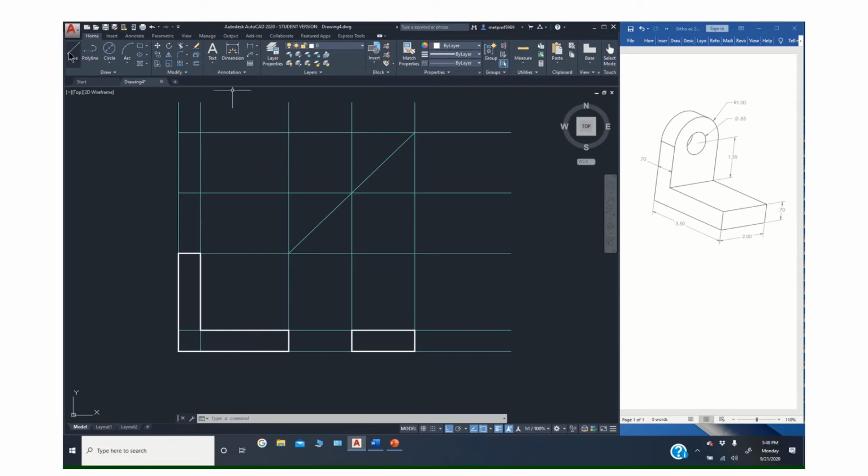So if I start like this, it's kind of a good starting point. Again, think about that face, and it's going to have a hole, but it's rounded off. So there's a couple ways I can get it. I can draw a semicircle there, and then I can trim it off, or I can just fillet the thing using the fillet command. And either way, if I remember, you have to hit R, enter. The radius is 1, enter, and then I can radius those corners. The other thing would be to just draw a circle and then trim it away.